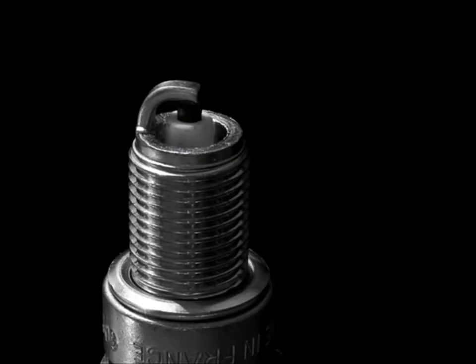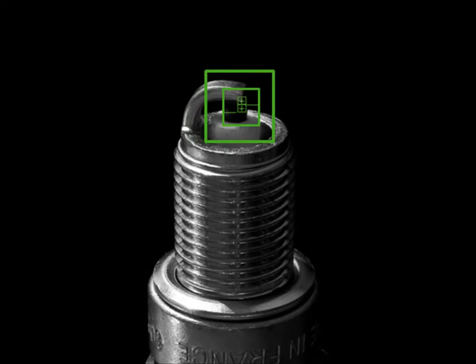Therefore, this gap measurement is an extremely critical spec for the part. We can use a camera and measure the spark plug gap by machine. This eliminates the need for a person to be there to measure and adjust the gap manually. We can automate the process and do it more quickly and accurately.